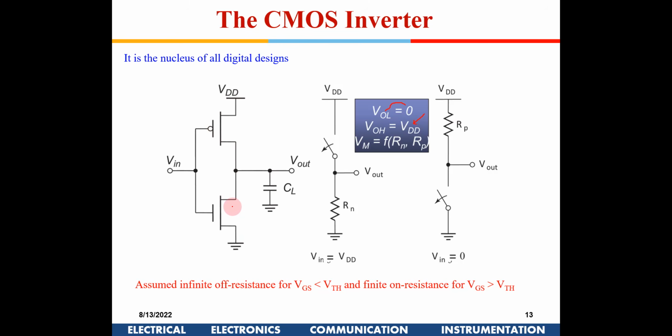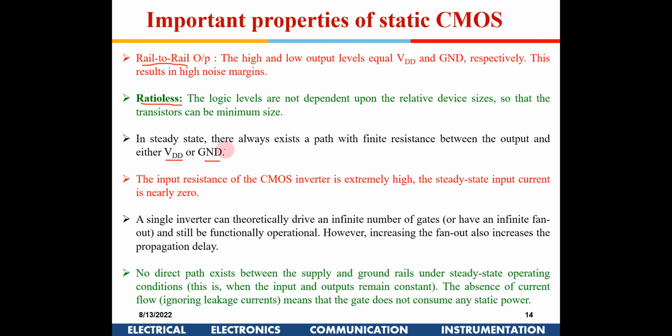That is not the case when we study pass transistor logic or dynamic logic. We will see that sometimes this node is floating. When I say static CMOS design, in that case it will be either connected to VDD or to ground. The input resistance of a CMOS inverter is extremely high.